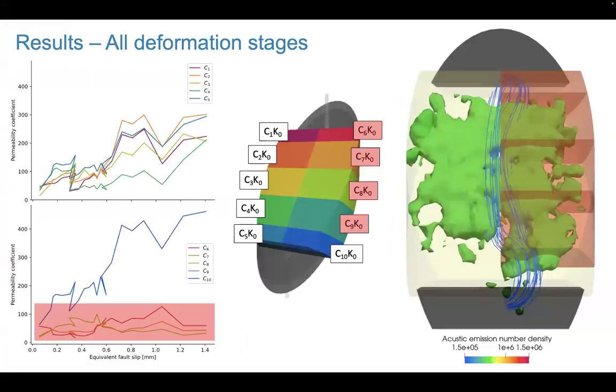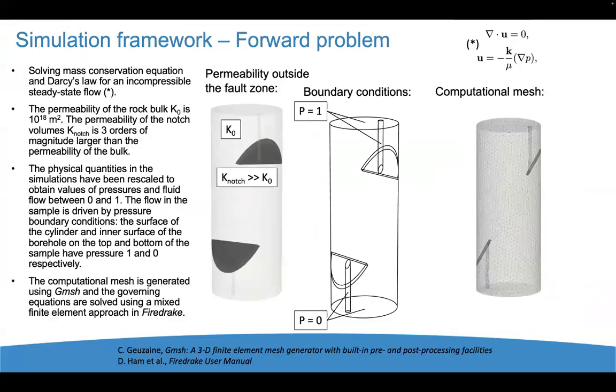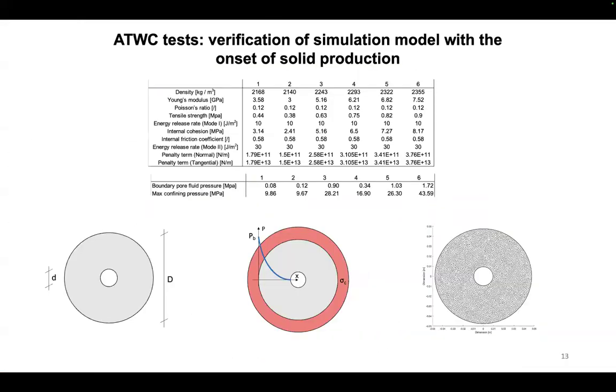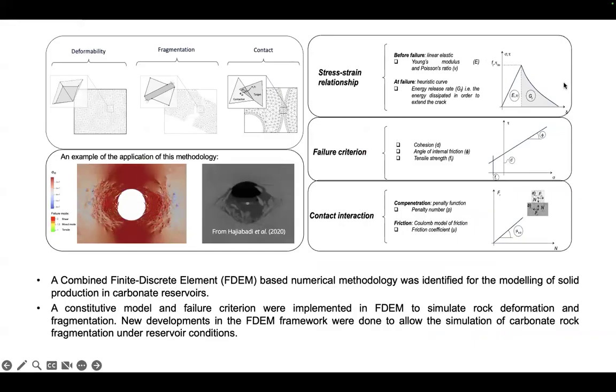Okay. So for what concerns the first model that I've shown, this FDEM model, it's a failure envelope, like here. Since you simulate the stresses in each point, you can have a definition of the stress, strain, etc., and you can then check whether the stress is greater or smaller than a failure envelope. In this particular case, we have a tensile cutoff so that we can simulate tensile strength and failure in tension, and we have a shear failure envelope defined by cohesion and an internal friction angle.